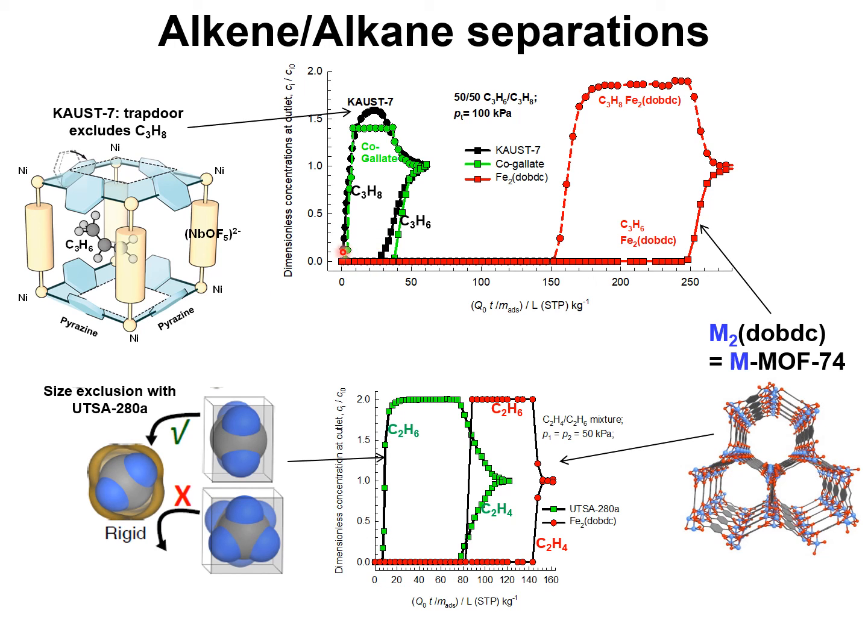The exclusion of propane from the pores has the effect that the propane that is present in the void spaces and within the pores during a vacuum blowdown operation is insignificantly small, and this results in a higher purity of the desired propene product.